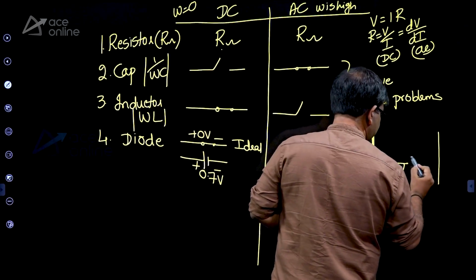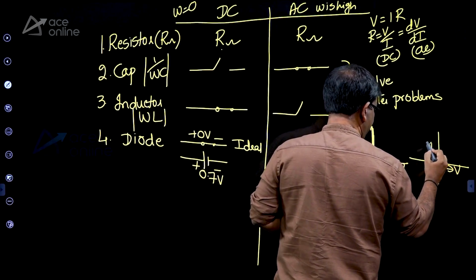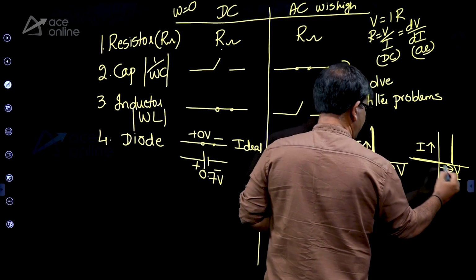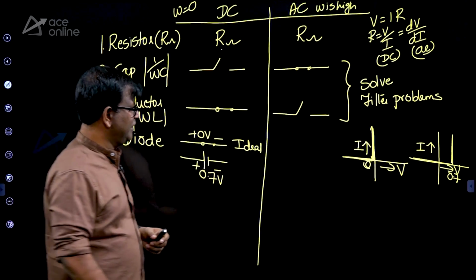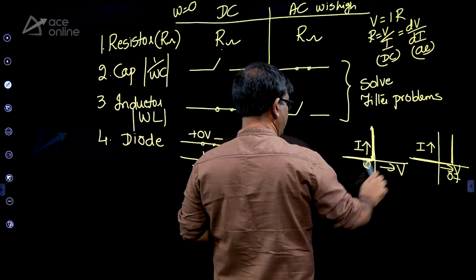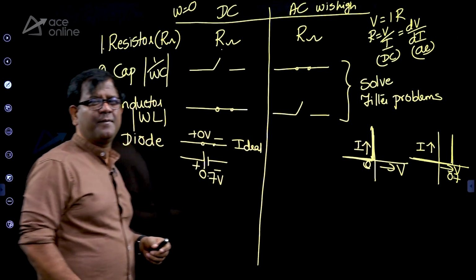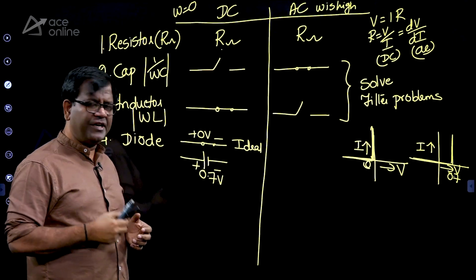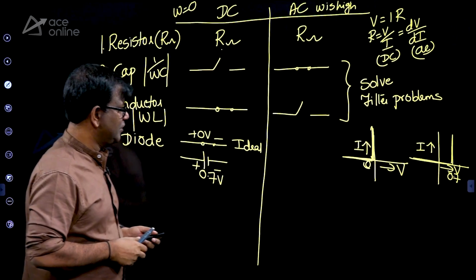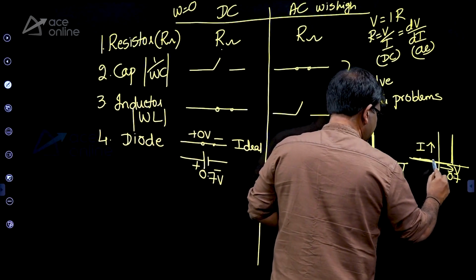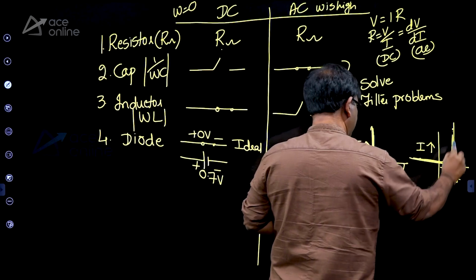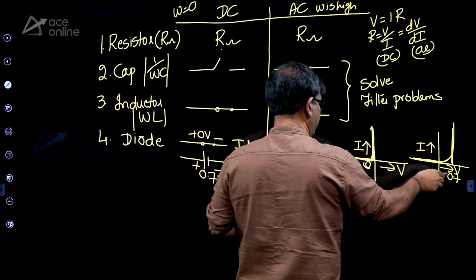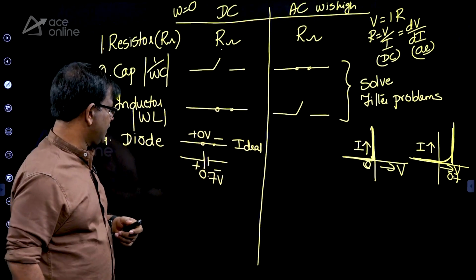Or if the diode characteristics the examiner has given are like this, piecewise, these are called the piecewise characteristics. Strictly speaking the diode characteristics are nonlinear, but nonlinear is difficult to solve. You have to apply some nonlinear methods like Newton-Raphson, so we are trying to make a compromise between simplicity and accuracy. The examiner himself doesn't care about the nonlinear characteristics, so he gives you piecewise characteristics.